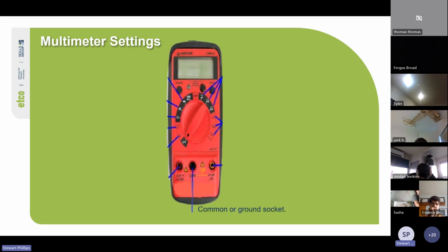Cool. So these are the different multimeter settings that you can get depending on your multimeter. So here you've got your diode check, so checking diodes and electronic components, checking which way they go. Continuity check, bell. So this is one you'd use when you're belling out faults. So you hook one end on a cable, you're not sure where it goes into a junction box at the other end, and then you can quickly tap the cables together and it'll make it beep.